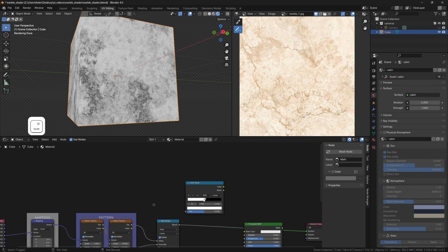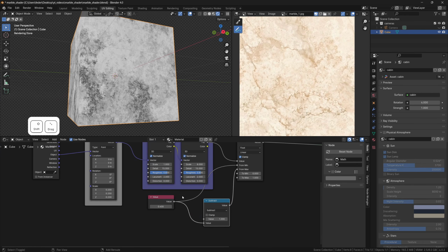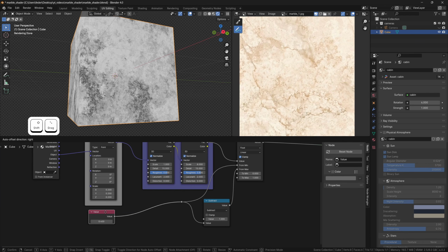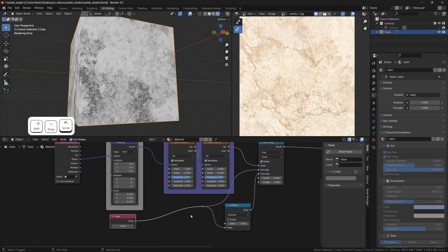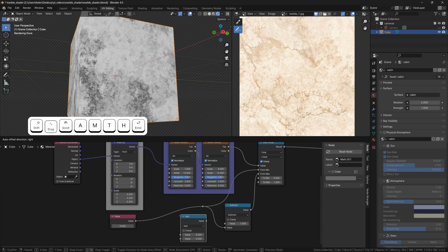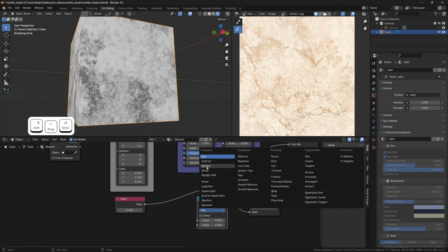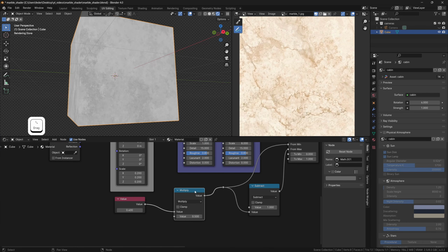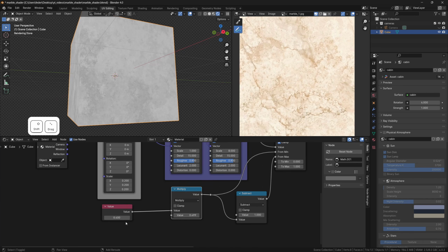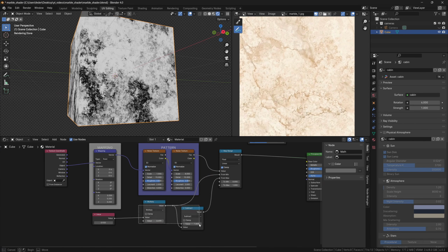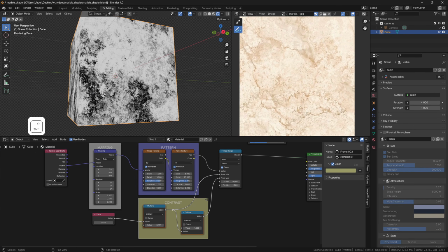Since this is not going to be useful in our case, and while I still want the input value to range from 0 to 1 to make it more readable in general, I'm going to limit its output with a math node set on multiply, where I would in fact multiply the input value by 0.499, which is the highest available value before any pattern's inversion. In this way, moving the input from 0 to 1 will indeed move the contrast from 0 to the max. I'll group again these couple of nodes to make the node tree organized.